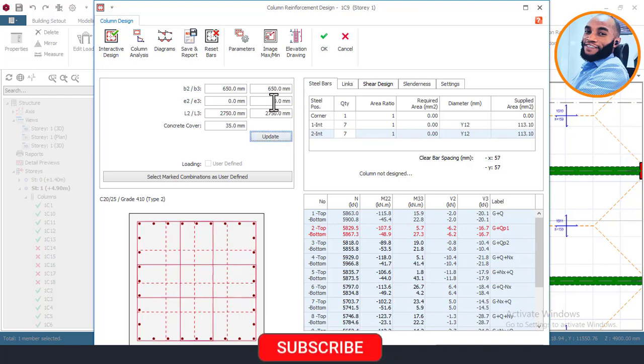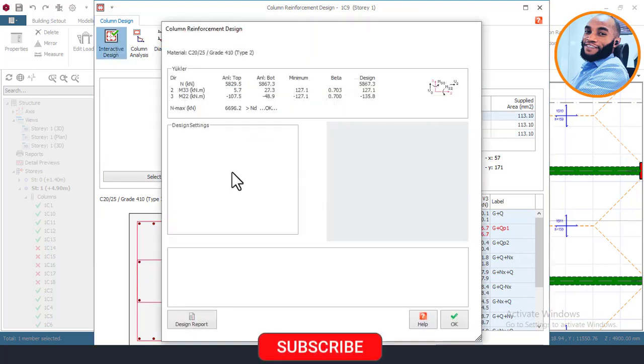Now this 0 here, because I was showing -1, so let the column just be at the center of the grid. Okay, that's why I'm using 0. Then I'll come here and click on reset bars, and then click on interactive design here and wait for it to show.